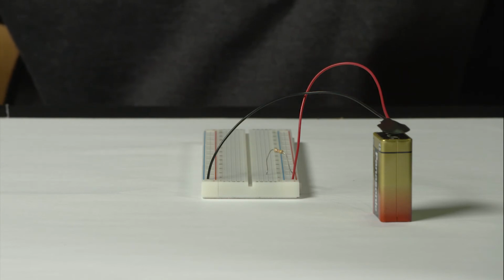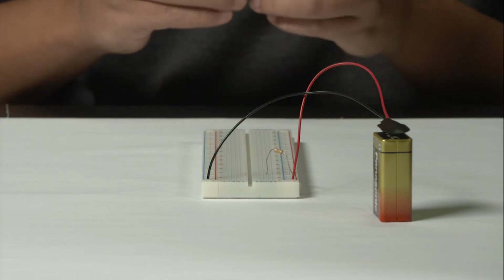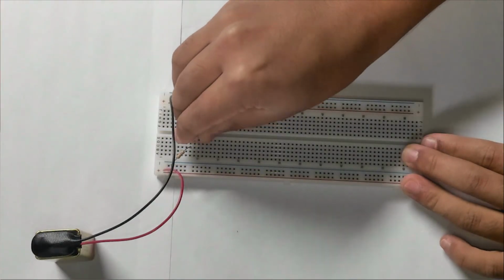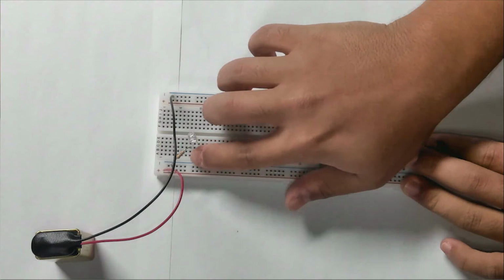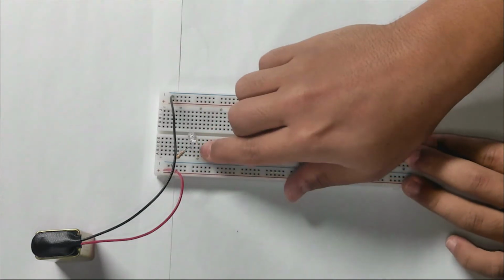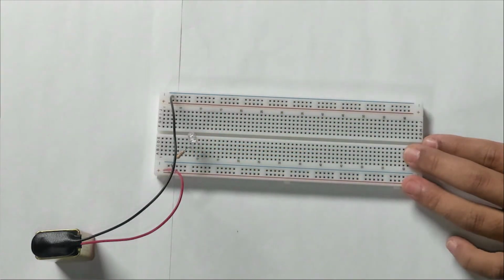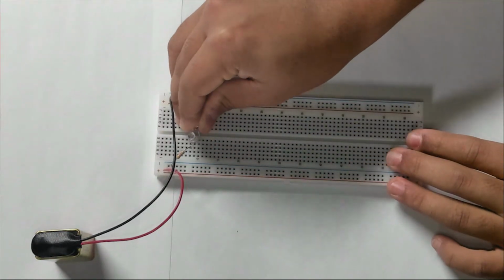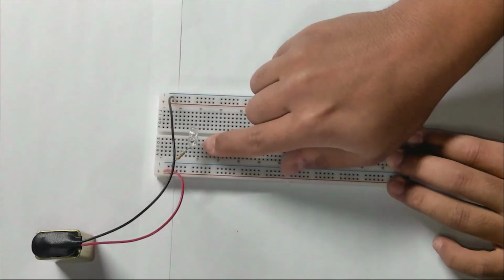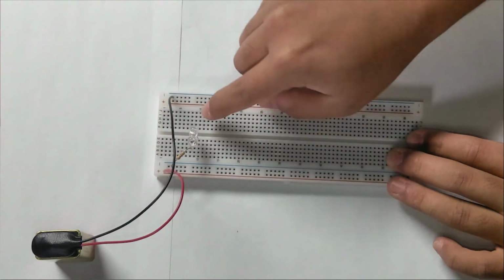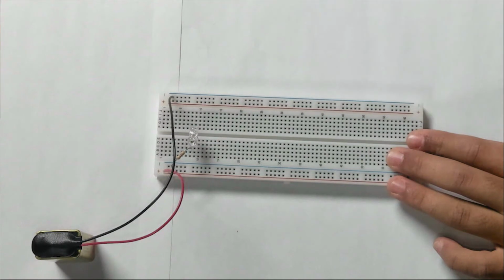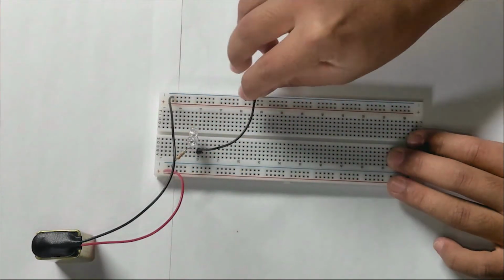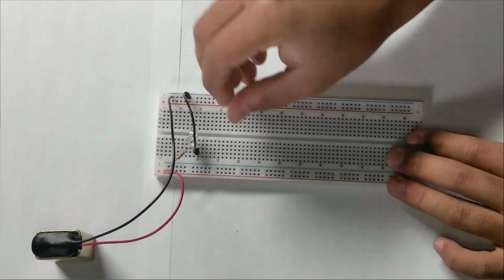So we're going to start by just adding 2 LEDs in parallel so we can see how the circuit's going to look. If we connect one LED to the positive side, or connect its positive side to the resistor, and then we'll take another LED and connect it right next to the other LED. Now, these 2 LEDs have their positive ends connected and their negative ends connected. And again, to complete the circuit, we want to connect the negative end of the LEDs to the negative end of our battery.